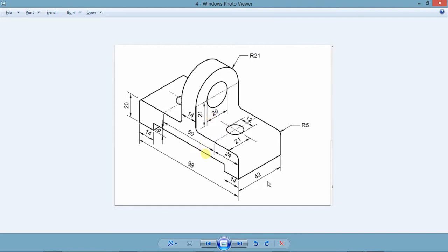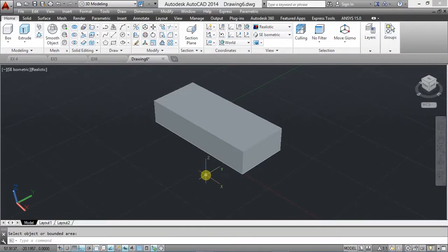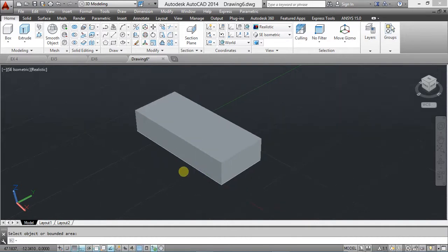If you want to remove this portion up here, 6 down here, you offset this line 14, offset this line 14, then offset it down by 6. As copy rather, okay. For a solid, you copy edge, this copy edge, okay. So this edge, and enter the direction.